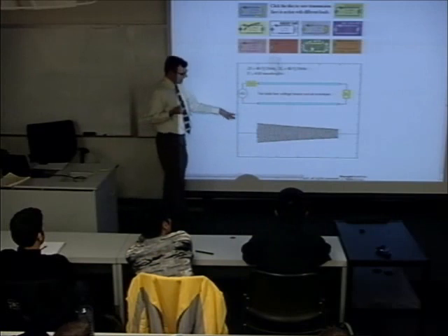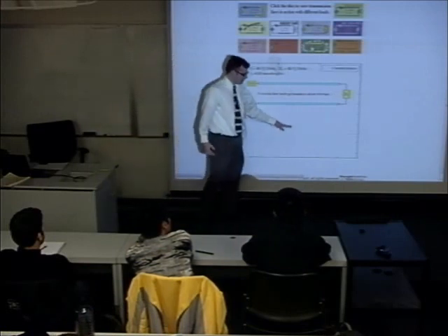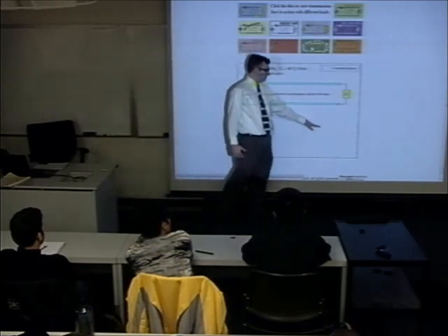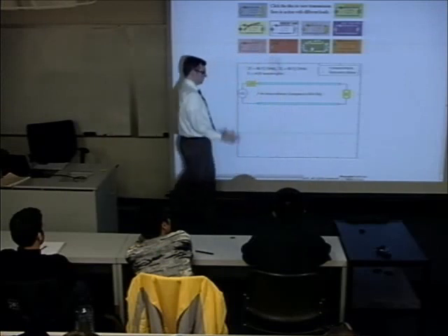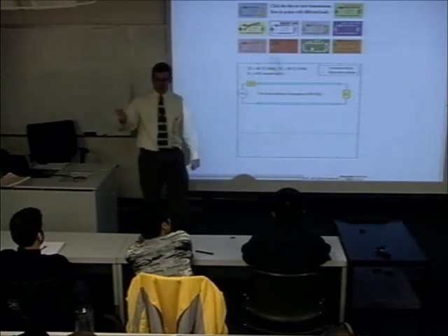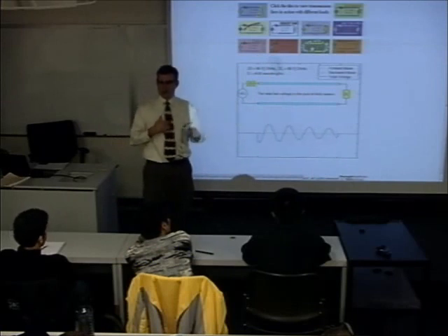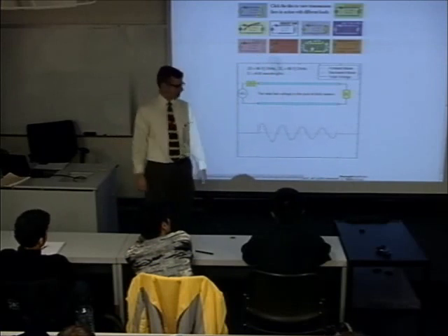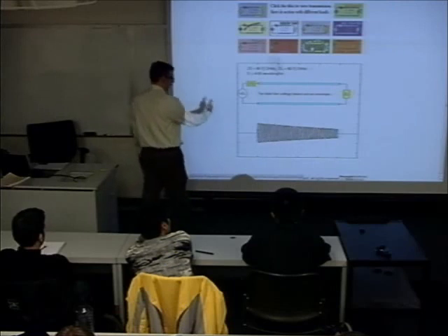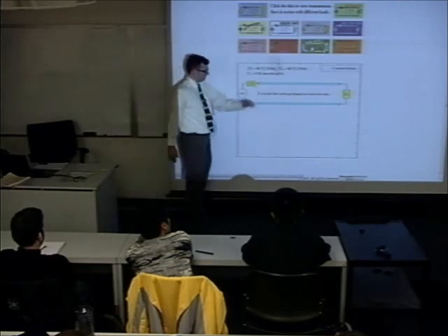What we really have is graceful exponential decay of the amplitude on the line. When you work through the math of the physics, that's what jumps out of a transmission line equation. You get exponential attenuation of the amplitude, and the envelope is a gracefully decaying exponential.